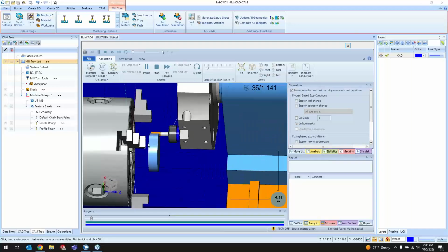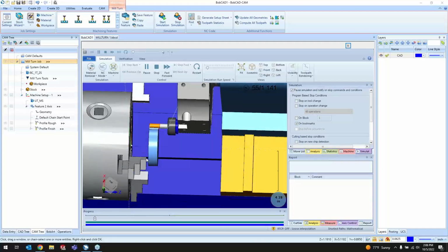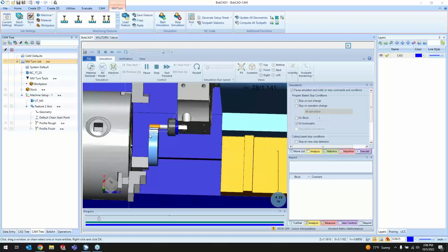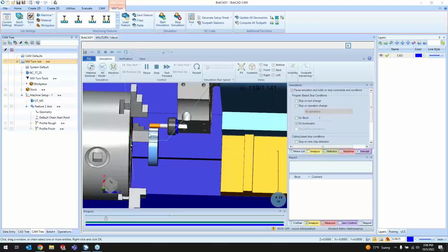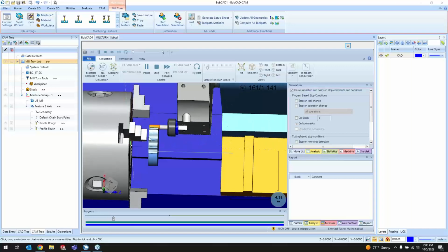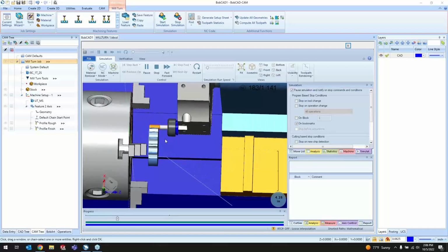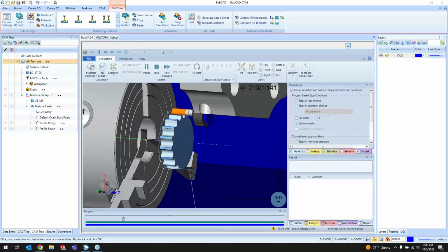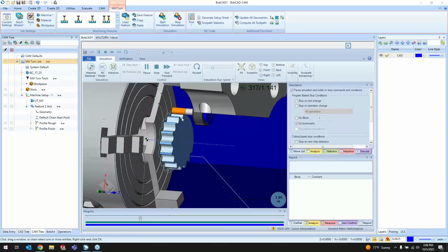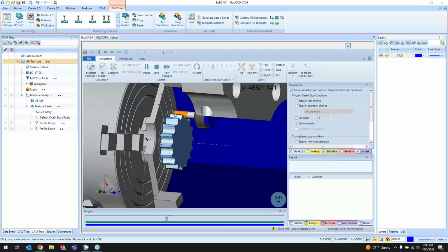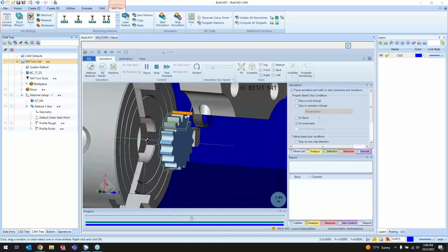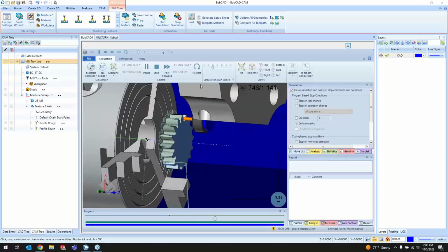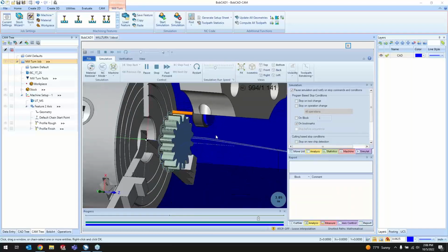The jaws don't lock on because the stock is outside of the jaw location. So a little bit of manipulating with that work offset. I would want to change that work offset XYZ, maybe move it back so that it'd be 2.5 inches instead of 3. But at least now there's not any errors there. Tool's large enough. The tool flute length is long enough to be able to cut into the gear hub there.